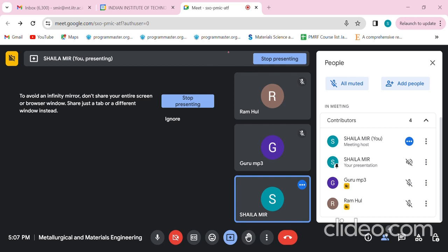It says if we have two species, A and B, and this is the phase which is having a minor solubility of B, showing the maximum solubility of B in A, and we have a liquid phase. In between these two phases, we have a mixture of our alpha, which is the solidifying phase, and the liquid phase. While here we have a mixture of both two solid solutions, which are alpha and beta, for example. So you are given what is the solidus line.